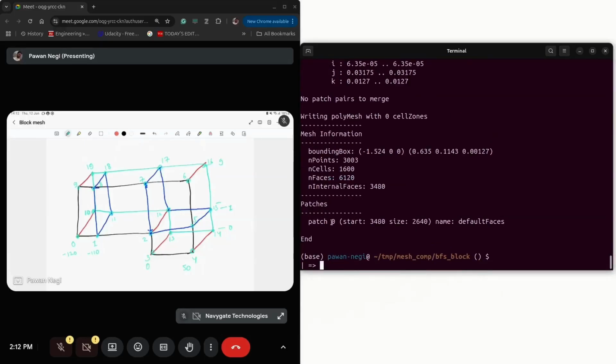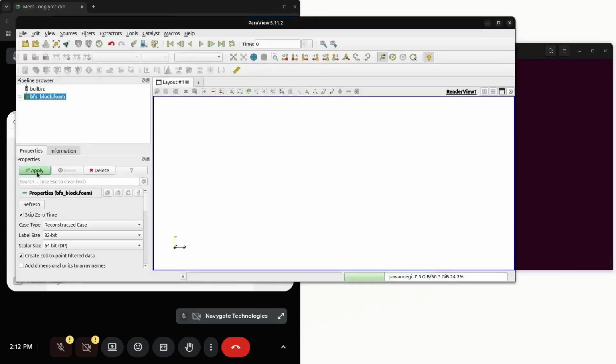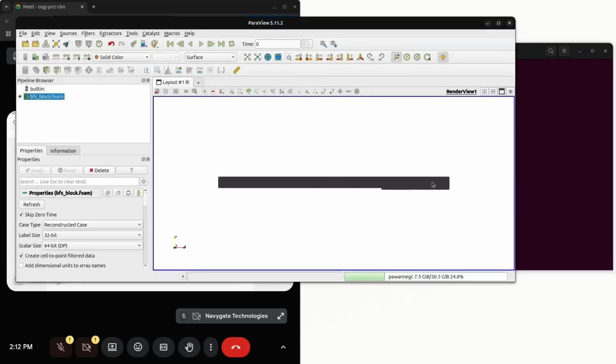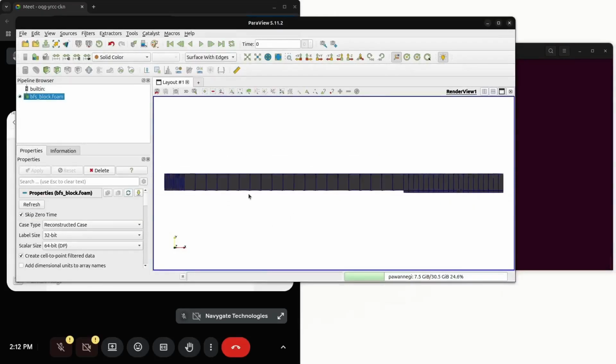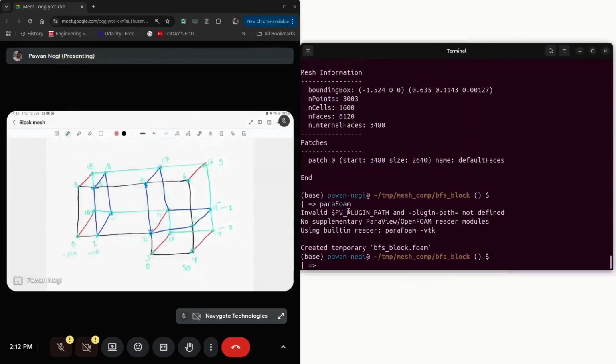Only one outer face was generated because we have not set labels to any boundaries. So it sets default face to all the outward facing boundaries. Run OpenFOAM. We'll see that the domain is created as we wanted, but the meshing is not what we expect. So now we'll see how we can set the grading so that the mesh is very fine near the step.